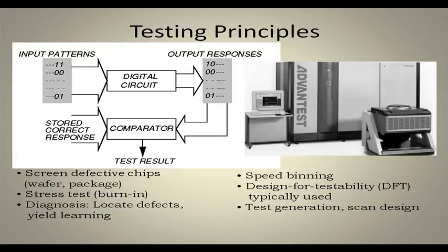Then the stress test. If the chip is operated for a number of continuous hours, then we see whether the chip starts malfunctioning or not. So, that is a stress test or burn-in phase.